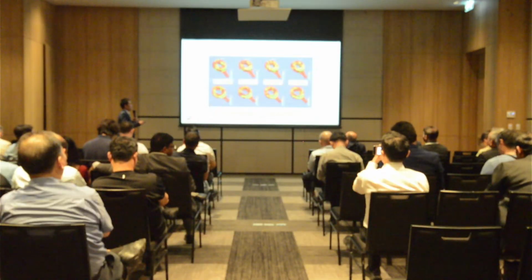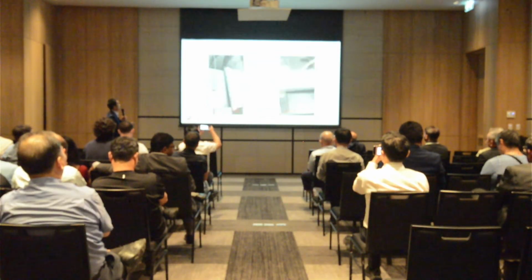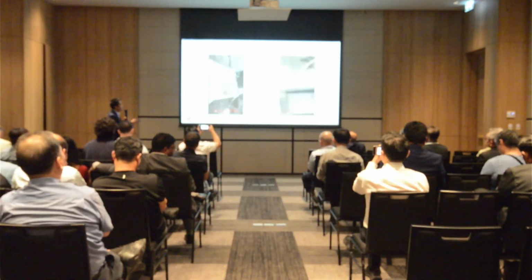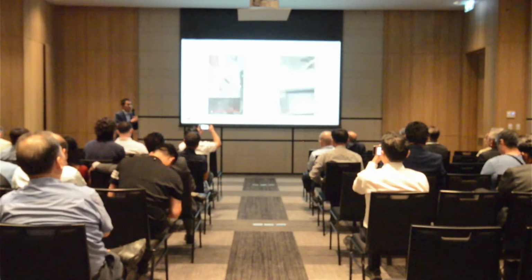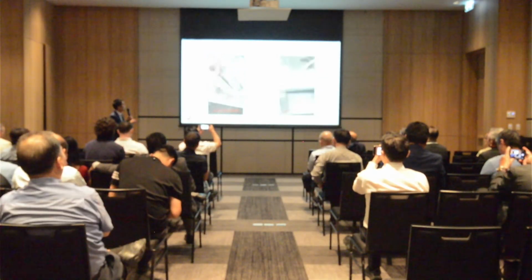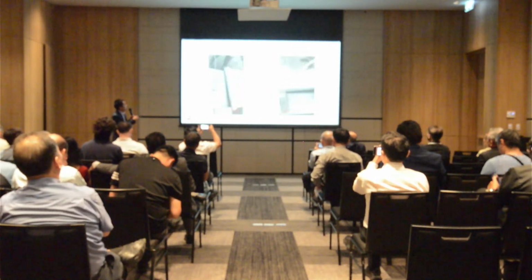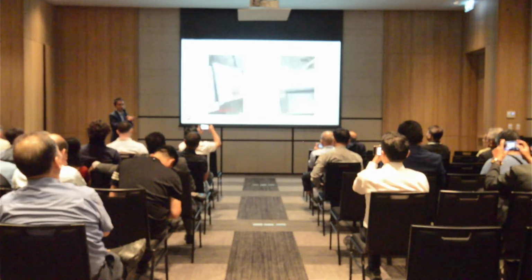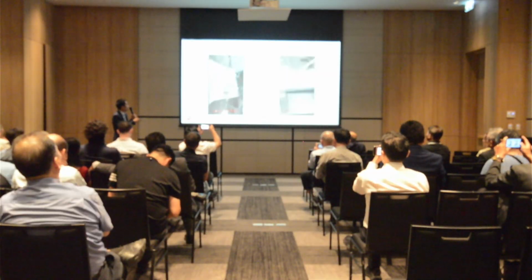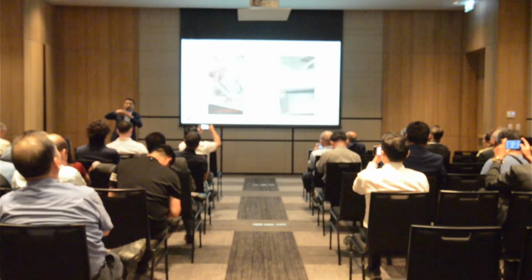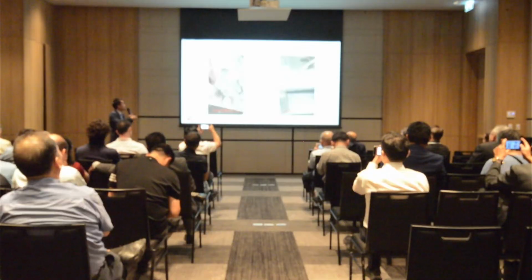Here I give you a real example. We did this very interesting test. This is fully liquid A380, an aluminum-silicon 9 copper 3 alloy. We ladle it and cool it in the air. You can see when we tilt it at 570, about the liquid eutectic temperature, and pour, it's like a solid, because the dendrites cooling in a big network combine together and it's not easy to cut.